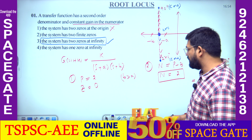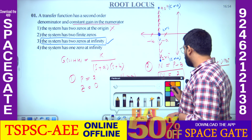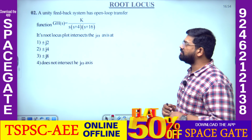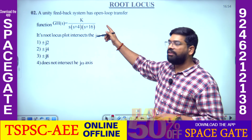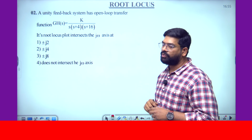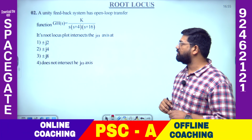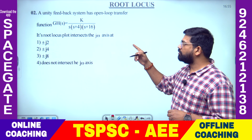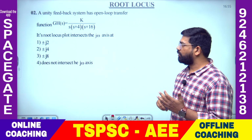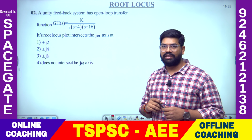Okay. Now let us move on to another question here. A unity feedback system has an open loop transfer function given as K by s into (s plus 4) into (s plus 16). Its root locus plot intersects the j omega axis at which point?